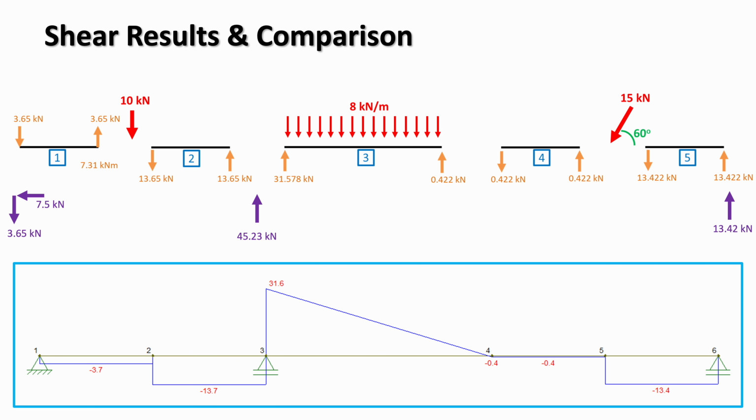Here we are looking at the shear forces from the stiffness method code and comparing them with the results from F-tool. The values at the top are the interpretation of the shear forces from our MATLAB results drawn in their true physical directions. Positive shear follows the local sign convention, and any negative values have been flipped so that the arrows represent the actual internal action. As with the axial results, this slide shows only the shear forces.